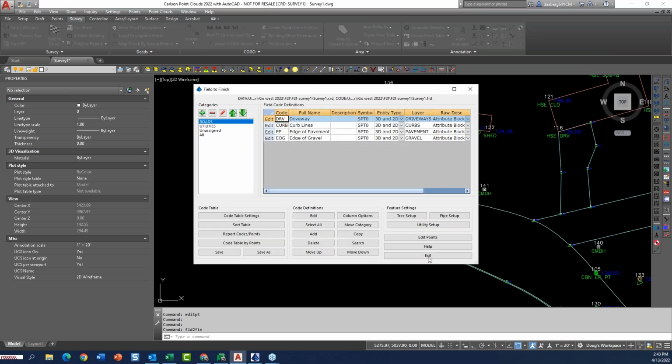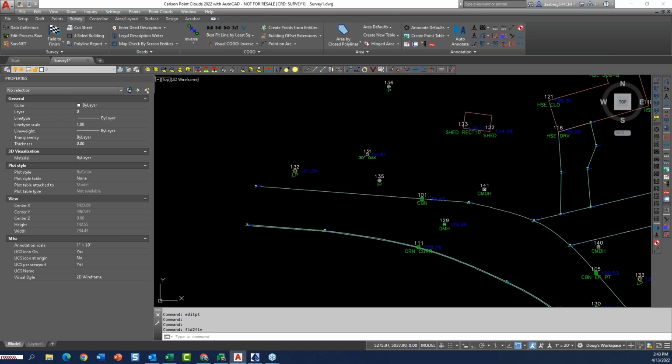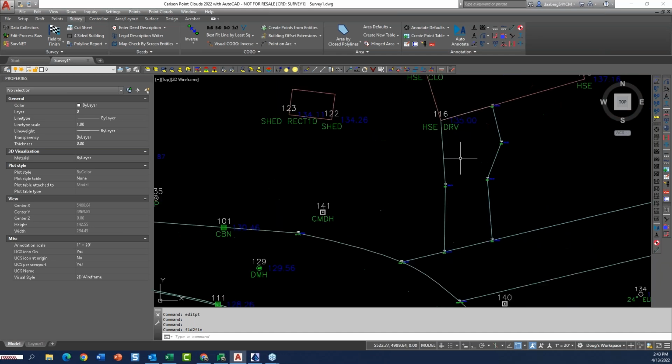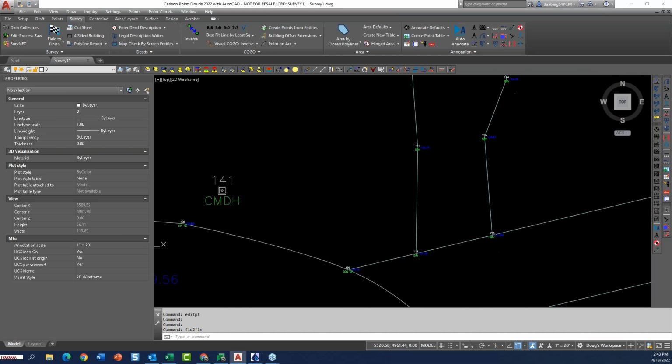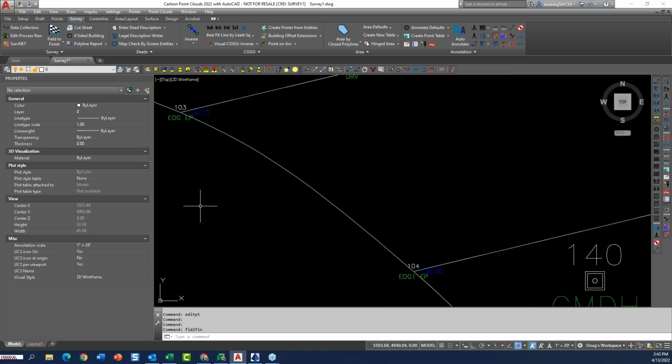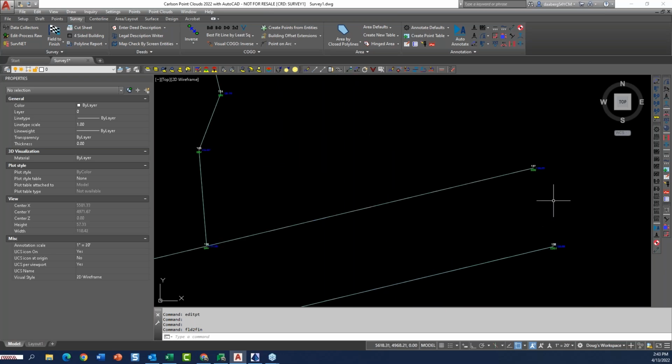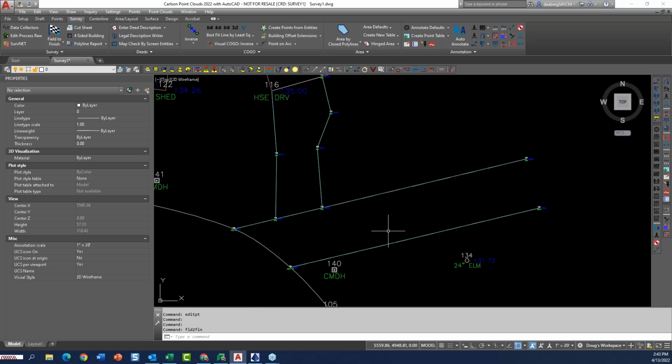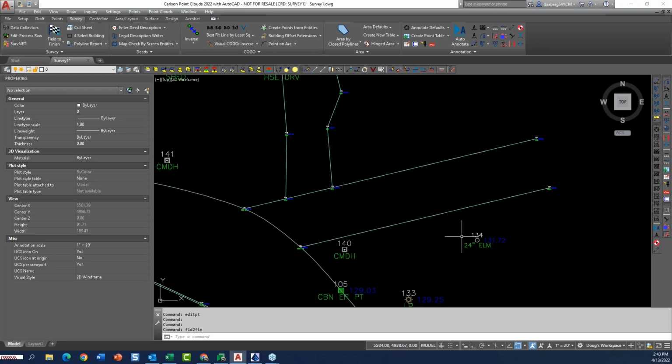As soon as it sees that code, EP, curb, DRV, whatever it is, it starts drawing lines. So I really don't have to tell it to begin. I just have to tell it when to end. Or like in this case, I went EOG on one side, EOG1 on the other side, because if I would have connected sequentially, I'd get a big Z here.